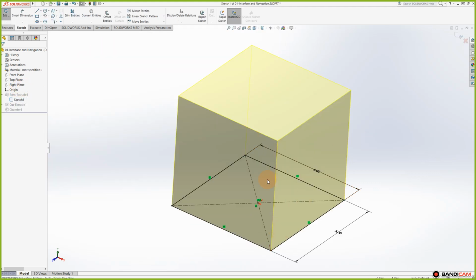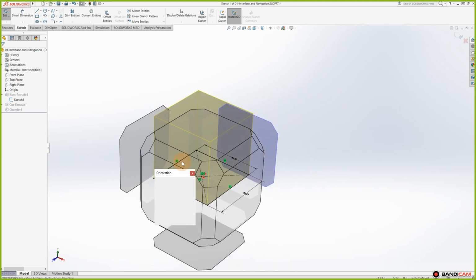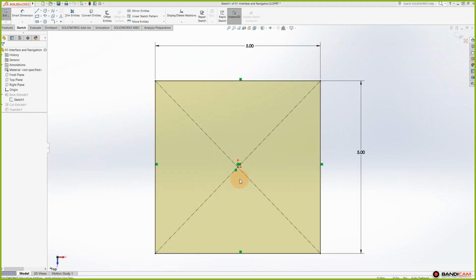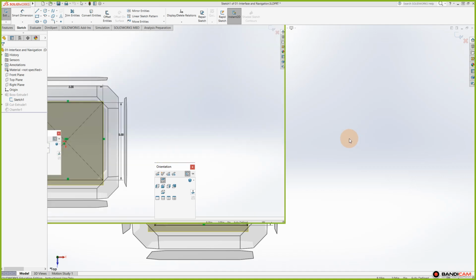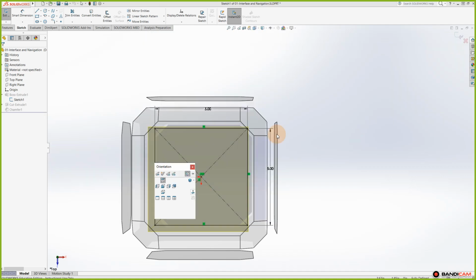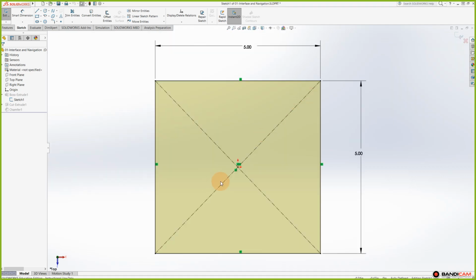From there, you see I have my sketch, go spacebar, go to view, and I have the top view. Again, how did I do this? I did the spacebar and the little icon right up to here, which is normal to, or as you see, Control 8 allows you to see the top view of the item you're working with, or the view I'm trying to adjust. Sorry. So now you see here we have our dimensions. It's already stored, and I could go back and change them.